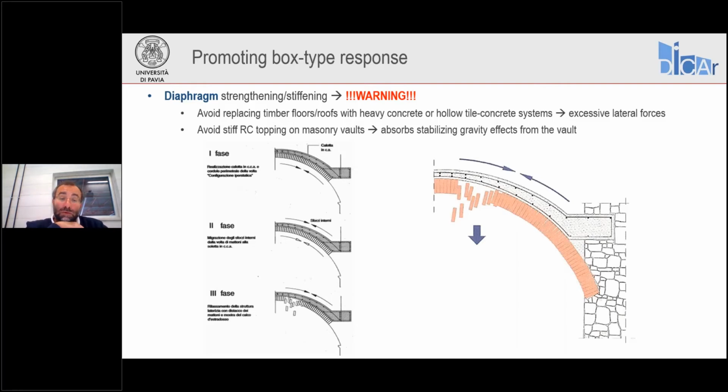So it will unload the masonry vault. And if we now shake the masonry vault, we may lose the bricks, except for those around shear connectors, because these bricks are not sufficiently compressed against each other anymore.